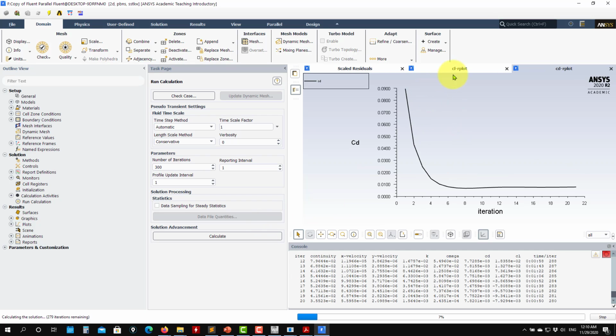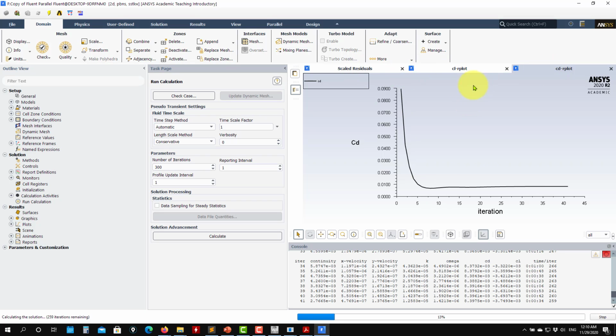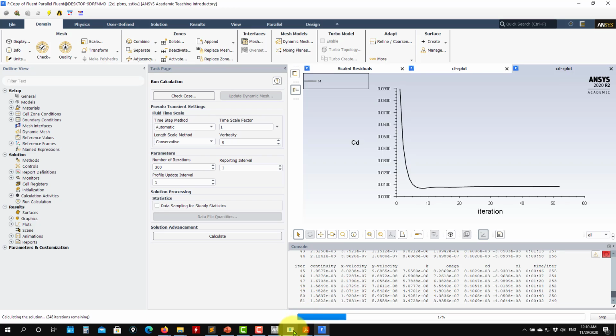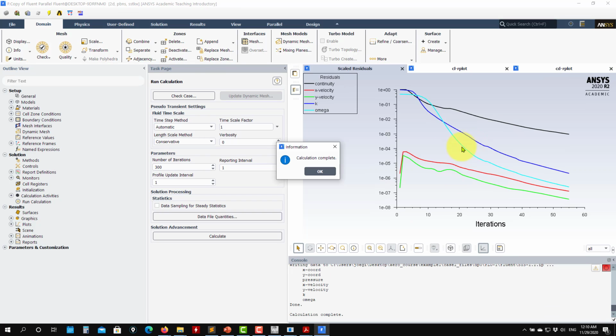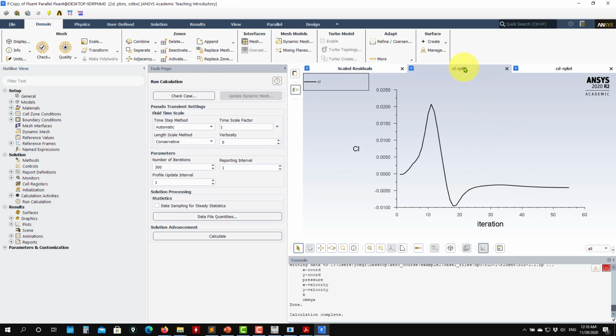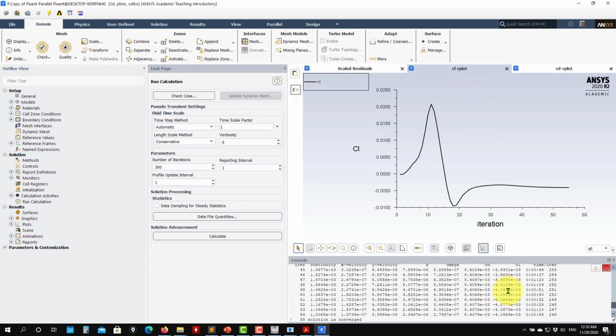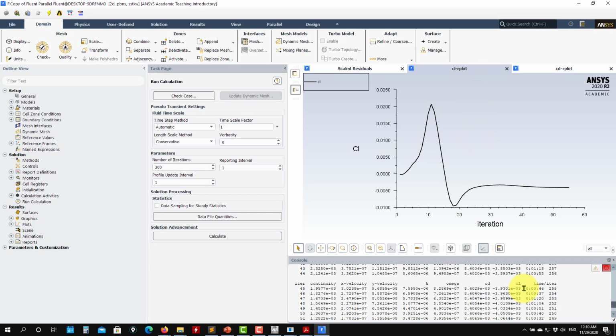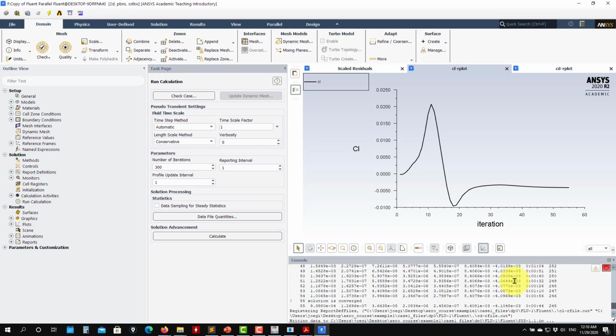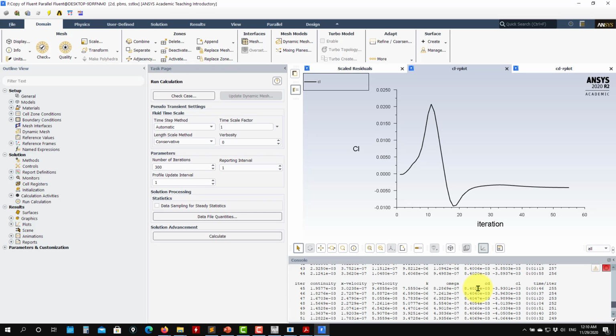And now it's running, but now let's compare. Okay, these results are at 0 degrees with airfoil at 0 degrees, but we're interested in CD. CL, we know that it has to be a value close to 0. So you look here, you see that CL is not exactly 0, but it's a small value. But CD is the interesting one. See that we have 0.008.